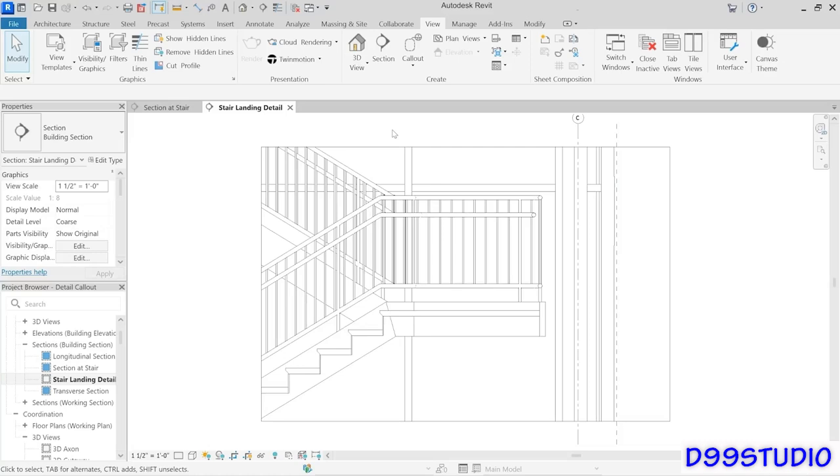But remember what we talked about back in the chapter on visibility. Don't start with how, in other words, hiding things or changing the way they look graphically. Start with what. What should be displayed in the view, and establish that first. And then if you get to a point where the elements that are displayed in the view aren't displayed correctly, then you can adjust how they display.